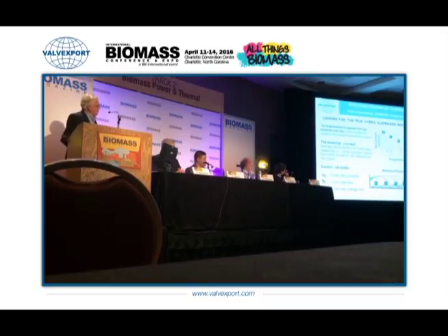The biomass will be thrown into the furnace depending on the air pressure behind the nozzle as well as the efficiency of the nozzle. Nozzles used today, we believe, have been designed more to cut cost, to minimize the cost of them, than to optimize the aerodynamics of their work. In other words, the idea is to put some air so the fuel is dumped or thrown or pushed, rather than truly positioned somewhere.